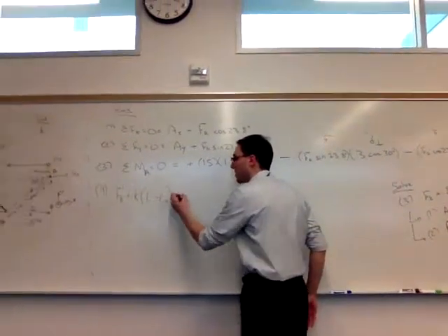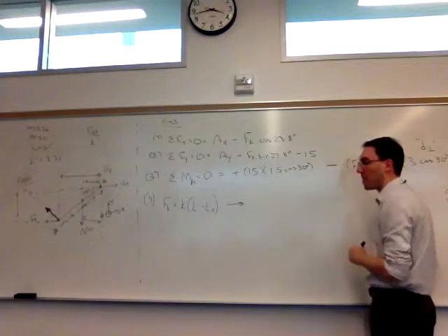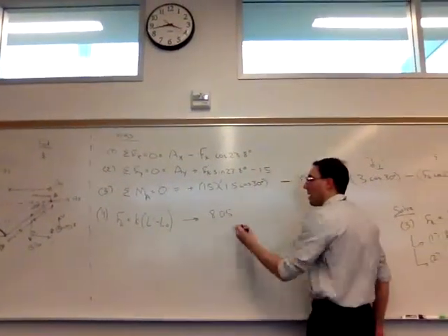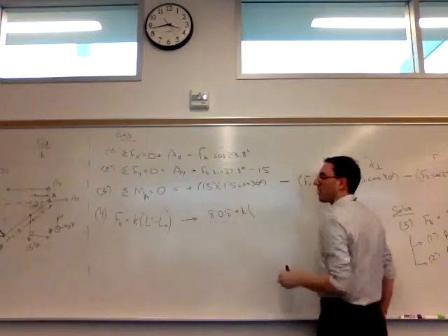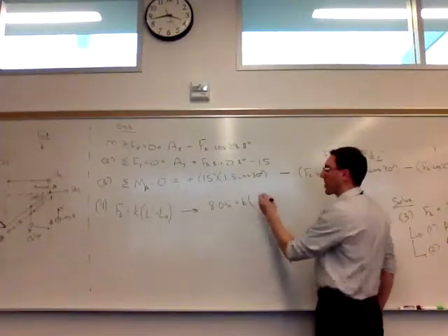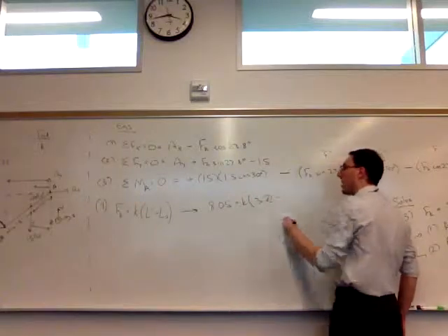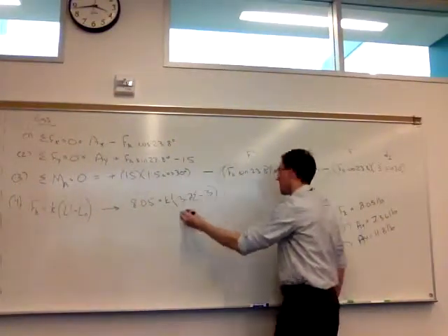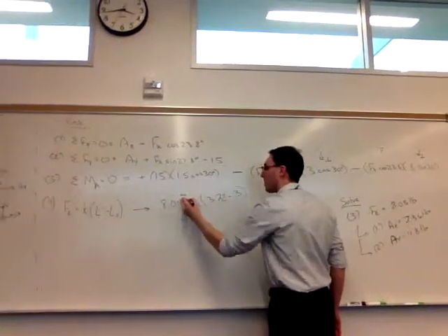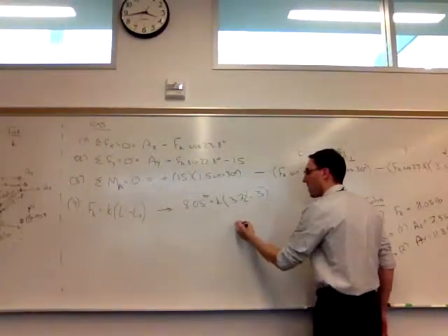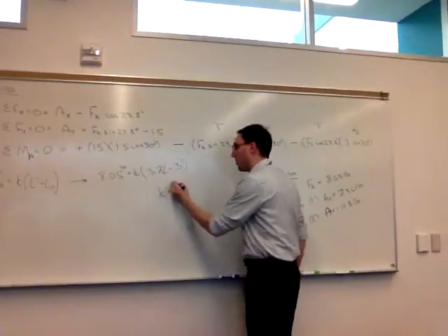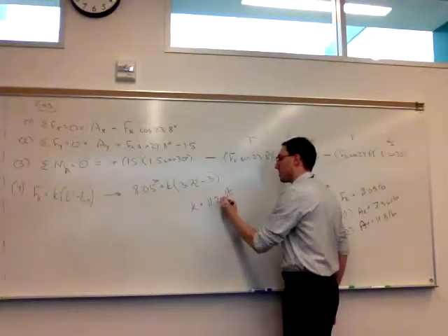So at this point we have numbers for most things: Fk is 8.05. K we still don't know. Through law of cosines, we know its current or equilibrium length. And through the givens, we knew it was originally 3 feet long. So solving equation 4, we get that the spring constant for equilibrium has to be 11.2 pounds per foot.